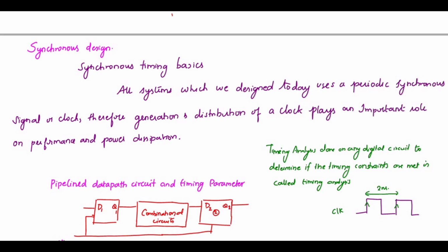So this must be exactly equal, right? If it is 2 nanoseconds, in the ideal world, the phase of the clock at the various points of the system is exactly the same, since we are assuming the clock path from the central clock distribution point to each of the registers is perfectly balanced.